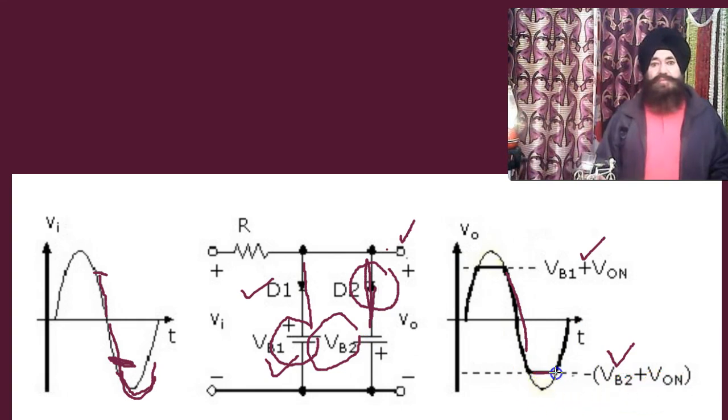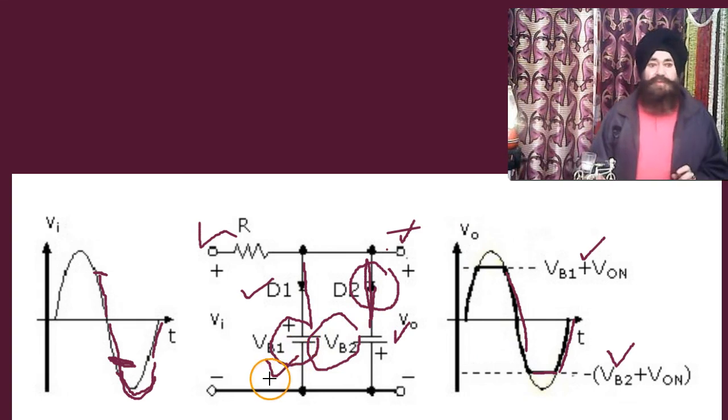The voltage remains VB2, and again the signal strength becomes weaker, and this voltage makes the diode reverse biased again, open circuit. Open circuit means whatever voltage is set here reaches to this end. So the same voltage appears again. So this process repeats. Okay, thank you. This is what clipping is.